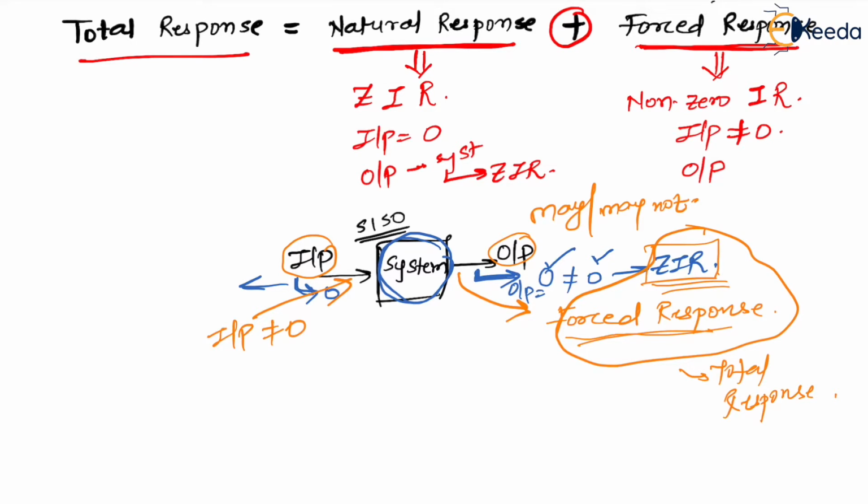So now let us see how to do so. In order to derive the equation, let us take our same x dot equal to Ax plus Bu state space model. Now let me take Ax to the other side, so it becomes x dot minus Ax equal to Bu. Now if you see here, is variable separable feasible here? No.